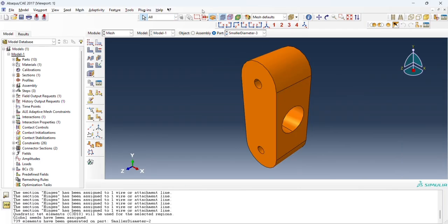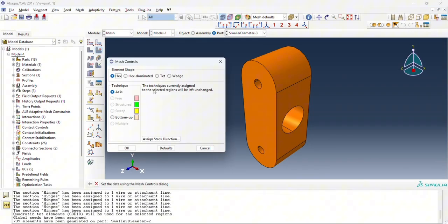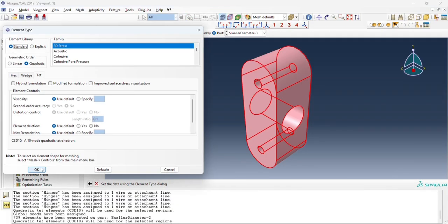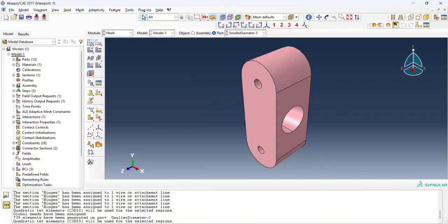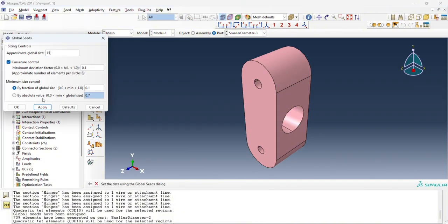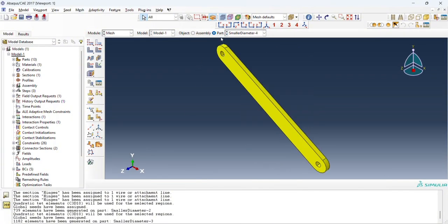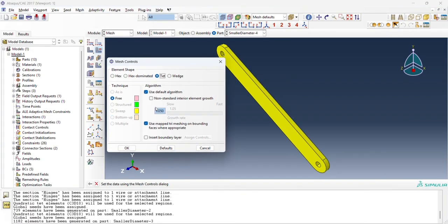and for all of them, the mesh size, we have to do the same step. First make it here 10, and assign, make sure the element type is C3D10. Then after that one, we have assigned the mesh size of 15. If we use a bit lower than that one, the node exceeds our Abaqus limit. And then 15. And for screw, we just do the same.